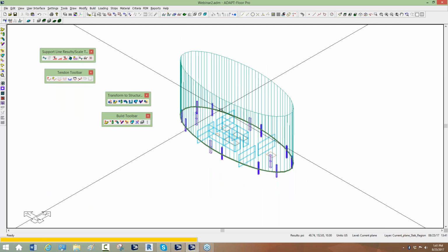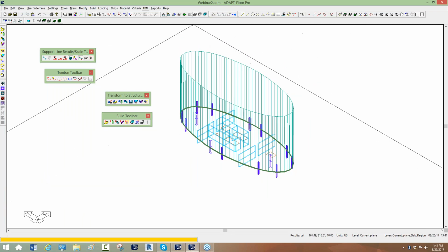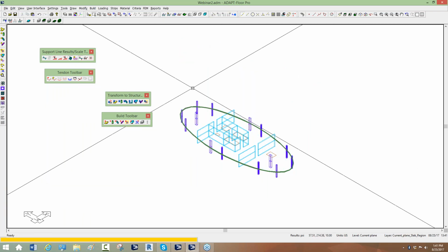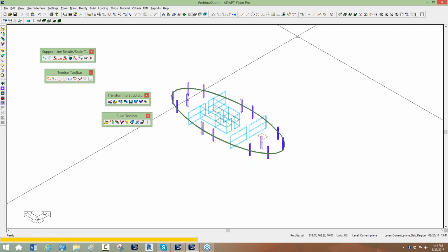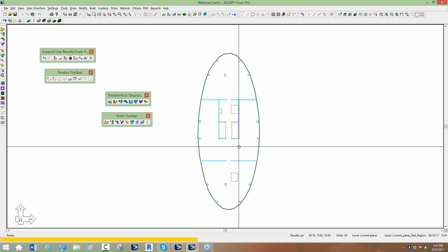So we have our model built. We added some cladding loading per the request of an attendee today. We have patch loading and cladding line loading around the perimeter. And now, the modeling is pretty easy, especially if we're evaluating just for gravity loads. Now comes a little bit more of a difficult part, which is how do we assess the slab for, number one, stresses, pre-compression, etc., based on the tendon input, and that's a function of design strips.